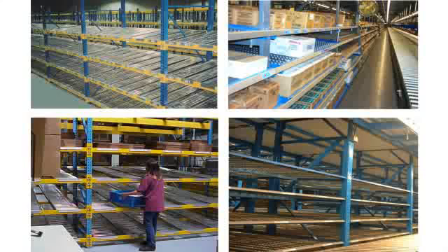Basically, like pallet flow, you load from one side of the rack and the product flows forward, and you unload from the other side of the rack. Loads can range up to 25 pounds a square foot. These racks are ideal for small parts storage or picking, such as small parts for automobile plants or shops, cigarettes, cosmetics, anything where you have broken down small items.